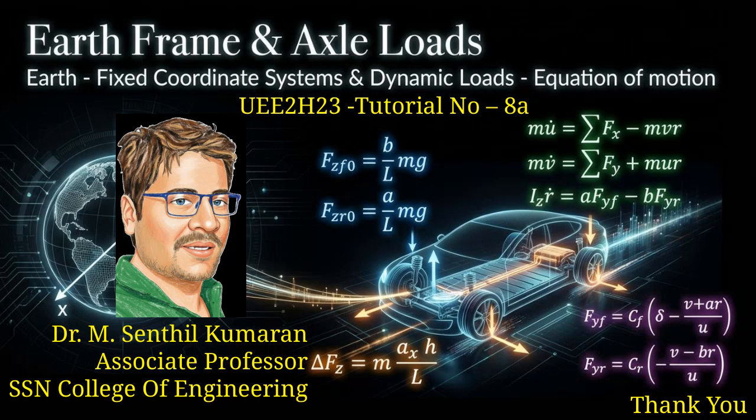For computing the steering release dynamics from 0.2 second to 0.3 second, set steering angle to 0. Residual side slip and yaw generate tire forces that drive decay in lateral motion and rotation. For computing the natural damping dynamics from 0.2 second to 0.3 second, with zero steering, coupling and tire forces continue to reduce yaw rate and side slip while the vehicle advances along a stabilized path. The final takeaway from the problem is a step-by-step integration exposes force coupling and shows how tire moments naturally stabilize the vehicle, which is the core insight for vehicle dynamics and control design.